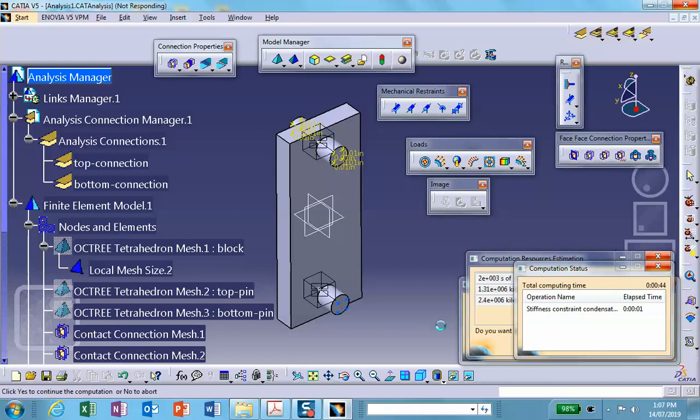Now, the good thing is that I saved it. If I have to kill it, then at least things don't have to be repeated. Let's just give it a couple more minutes and see how it works. In all likelihood, I have parabolic elements. Small mesh, contact, parabolic elements is a triple whammy. And then I have a computer which is about 8 years old, and that by itself is a problem.